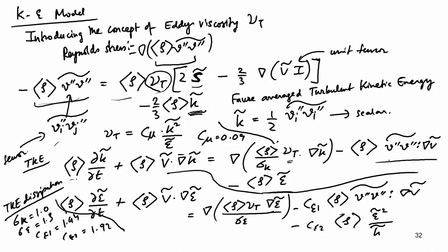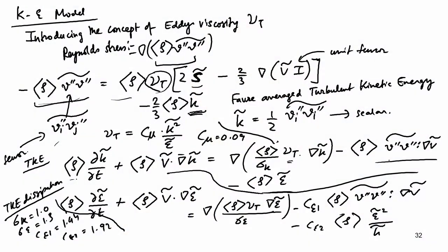Of course, you cannot describe the flow totally yet, because you don't know the density, and density is dependent on temperature. That is how combustion couples with turbulence through density variation at one level. Combustion creates heat release, which increases temperature, temperature reduces density, and density goes into your continuity and your momentum equation. So this is one level of coupling. Of course, you will see that there is another level of coupling also, because combustion leads to consumption of the species, and that has other sorts of couplings through how it couples with temperature. We will come to that, but now at least we have the flow sorted out.